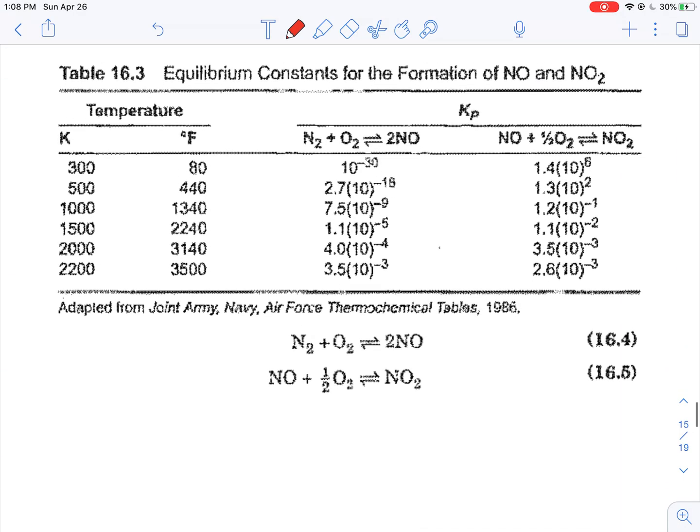Okay, so again, the nitrogen oxides are typically generated from coal-fired power plants or fossil fuel combustion. Here I just want to let you know that temperature will affect a lot of things. It's raising the temperature from room temperature, which is around 300 Kelvin, to 2200, which is around the combustion temperature. Here is the equilibrium constant for this nitrogen and oxygen reaction, because whenever we burn fossil fuel, we also introduce nitrogen and oxygen inside. These two species will combine to form nitrogen monoxide. You can see that the equilibrium constant increases exponentially as we increase the temperature.